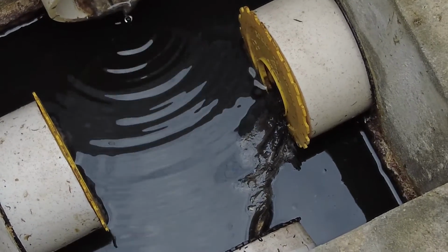And you may get a high BOD or suspended solids, and think your unit is not working properly because it's throwing off BOD or TKN or combined nitrogen, and you'll make a different decision on how you adjust that treatment system. That's not going to be a good thing because you'll be chasing your tail. So let's get into samples.